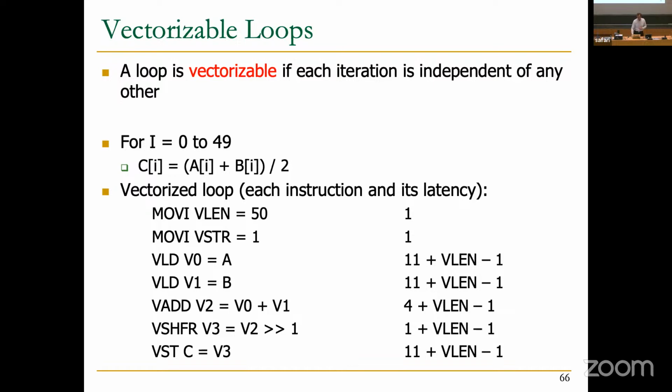And you can see immediately that there's no branch here. We got rid of the branch. And we have only 7 dynamic instructions. 2 of them are setup instructions, and the remaining 5 are actually the instructions that do the bulk of the work. Now, this is where the energy efficiency comes from. You can see that the control overhead of, I don't remember, 14 instructions is gone.